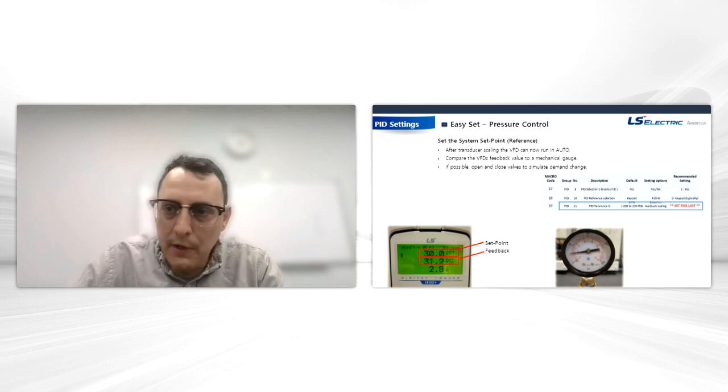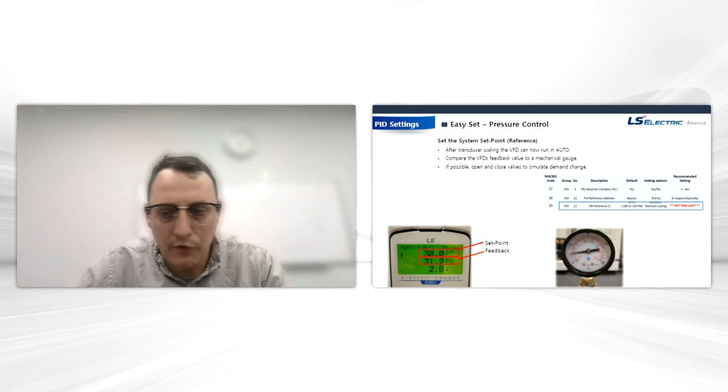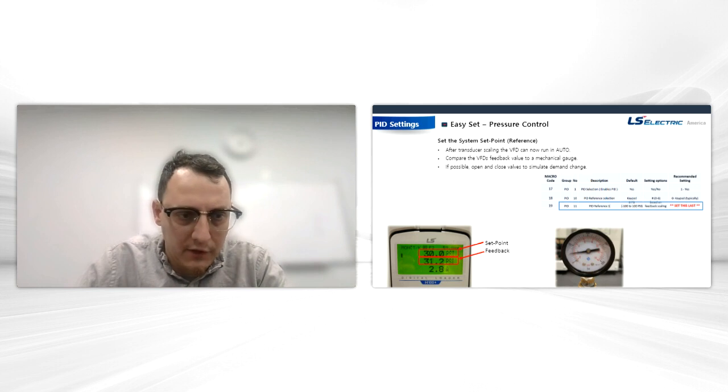always recommend to people when they're doing a startup and trying to troubleshoot. They say, oh, it's not working right. I'll say, all right, well, let's compare the drive's feedback, what the drive is seeing electronically, versus a mechanical gauge and make sure they match. That way you can tell if the drive is set up correctly or if there's some other thing going on that we're not aware of. So it's just basic troubleshooting.